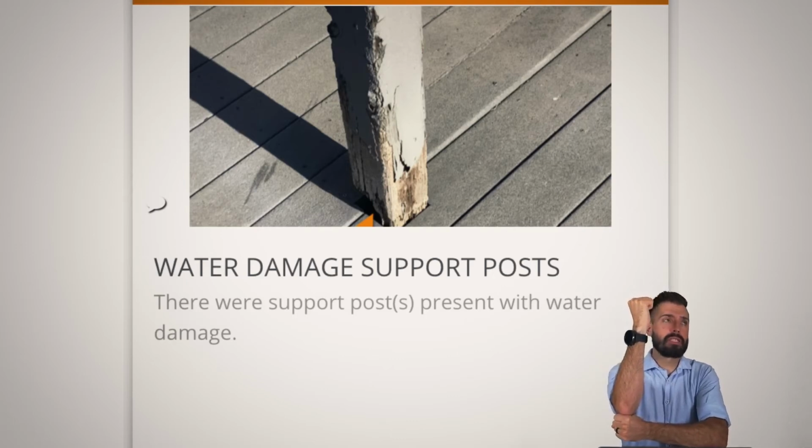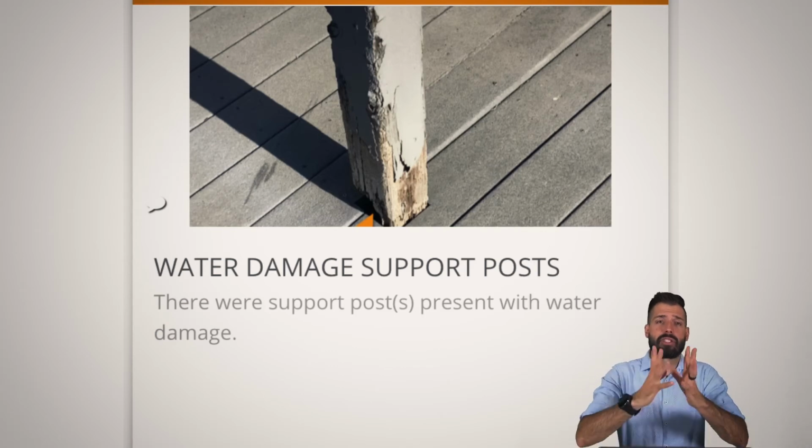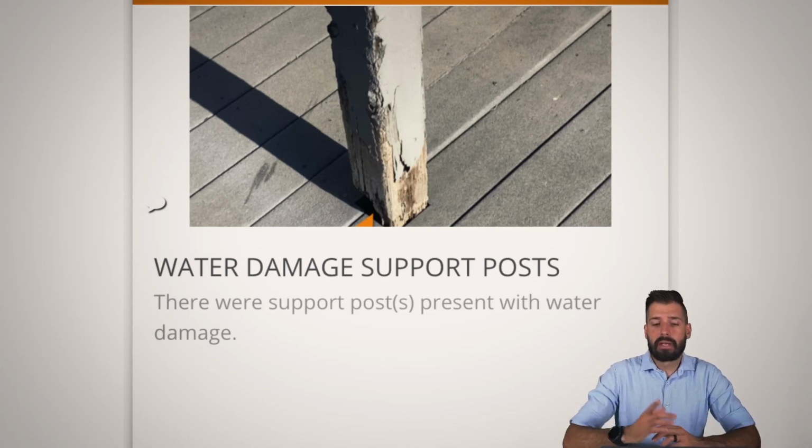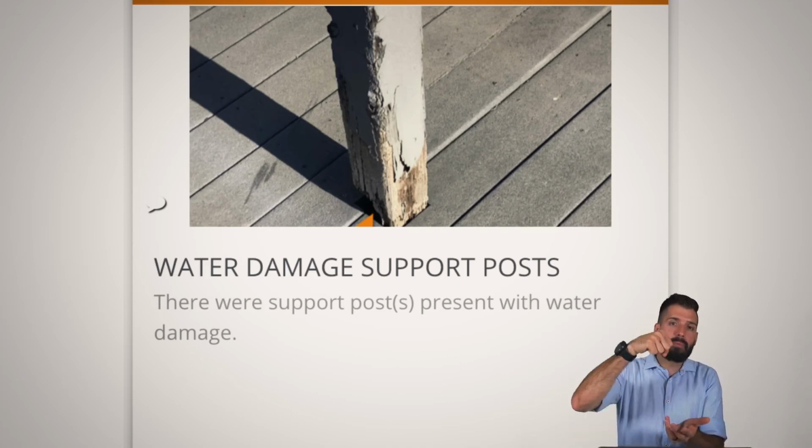So that way it would be a piece of metal. You don't necessarily want to put it directly onto concrete because that concrete can actually move moisture up into the wood. But it's the end grain that you really have to watch out for. Wood is like a vampire. After death, it's still sucking. And so you got to be really, really careful with wood, because if anything gets into that end grain, it's going to suck up all of that water.